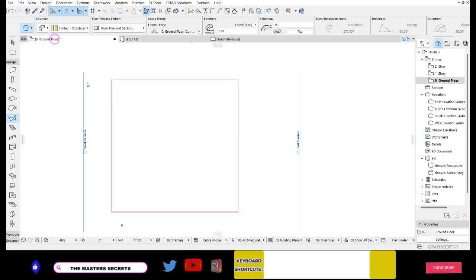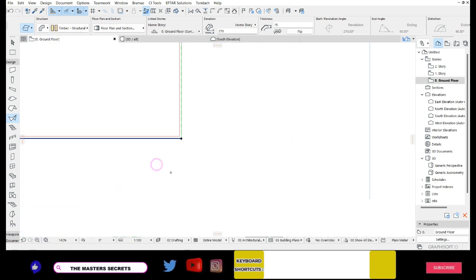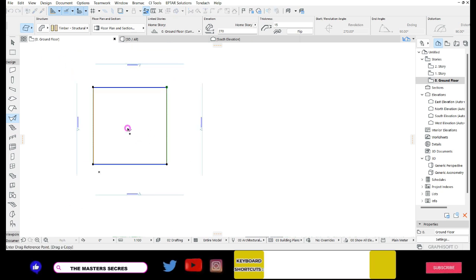Go to the ground floor plan. Click on the shell tool. And let's drag a copy. Ctrl Shift D to drag a copy. Drag a copy and send it this way. Let's send it this way about 40 meters and make sure it's at 0 degrees.